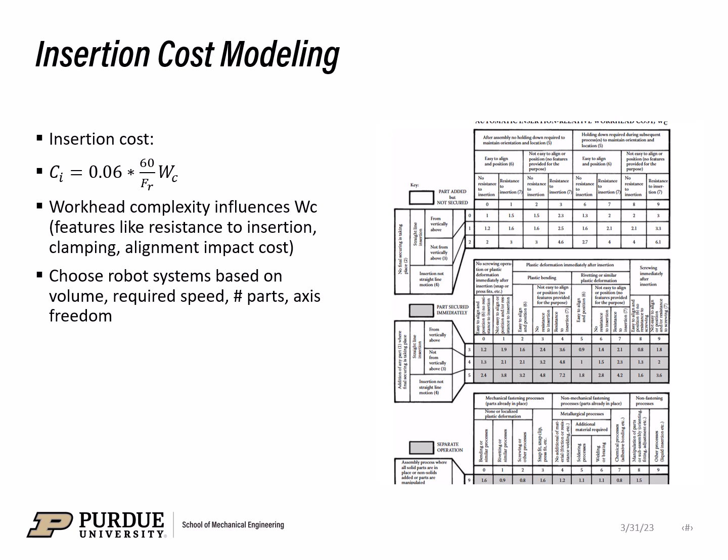Most robotic grippers handle Z-axis insertions really well, but struggle with lateral misalignment. So that's something to take into account when you're designing the part, is having as many of those Z-axis alignments as possible. Common design fixes to make a part more easily insertable could be having tapered lead-ins, spring-loaded guides, or even ultrasonic sensors that help verify the fit.